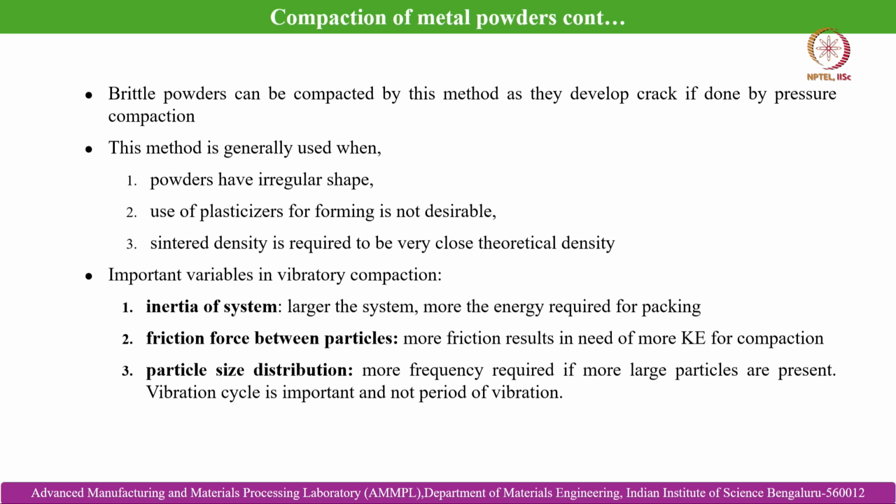So, this method is generally used when powders have irregular shape. Use of plasticizers for forming is not desirable, and sintered density is required to be very close to theoretical density. So, important variables in vibratory compaction: inertia of system. Vibratory compaction is basically where the mold is kept